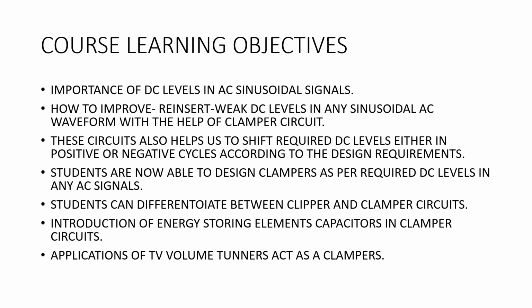So now the course learning objectives of this topic, clampers. There is an importance of DC levels in AC sinusoidal signals. How to reinsert weak DC levels in any sinusoidal AC waveforms with the help of clamper circuits. These circuits also help us to shift required DC levels either in the positive or in negative cycles according to the design requirements. Students are now able to design clampers as per required DC levels in any AC signals.